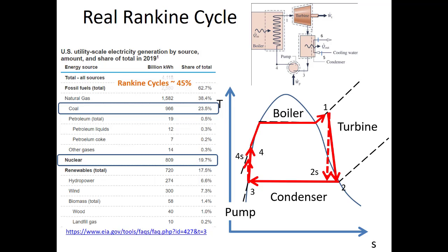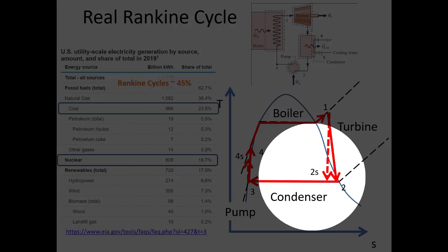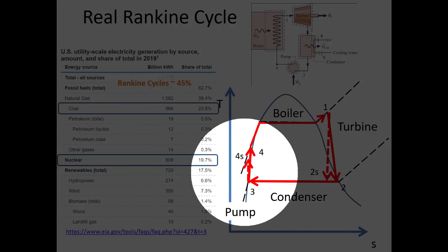So now we have high pressure steam and we can go back through that turbine. So knowing how to draw these TS diagrams is important. We remember when we're talking about ideal turbines and pumps, if we can make a series of assumptions about the turbine and the pump, we can treat these as isentropic turbines and pumps, where they have this vertical line going between state 1 and state 2s, which is the isentropic outlet of the pump, or of the turbine in